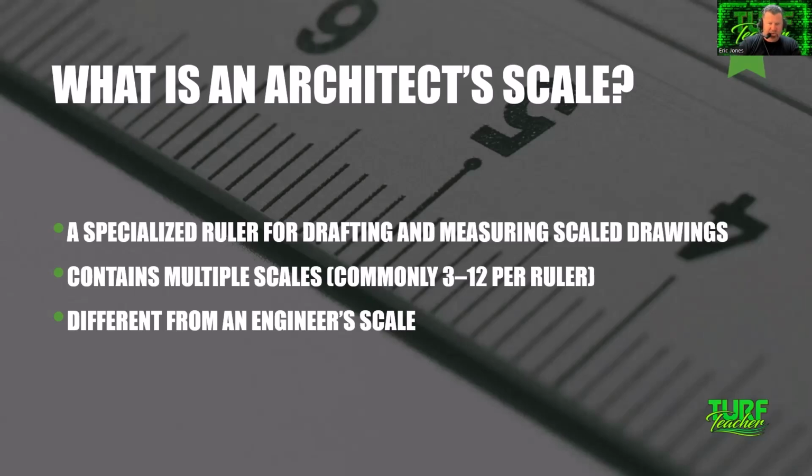As I progressed through my college career, I would come home and help Dad out. Of course, he'd have blueprints out, and he'd be taking a little tape measure and scaling the drawing. I'm like, Dad, you want me to get my scales out of my bag? He's like, no, son, I don't need a set of scales. And I'm like, what do you mean? He said, it's 1/8 of an inch equals a foot. So every inch on this tape measure is 8 feet. He was scaling that landscape based off that. Actually, he was estimating a job when that happened. So if you're good with this, you can be good with the scales.